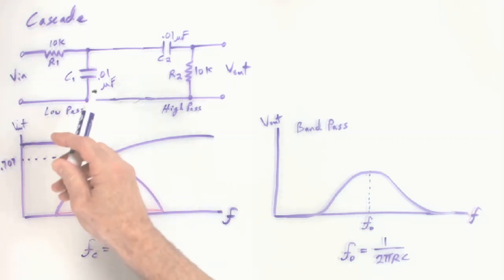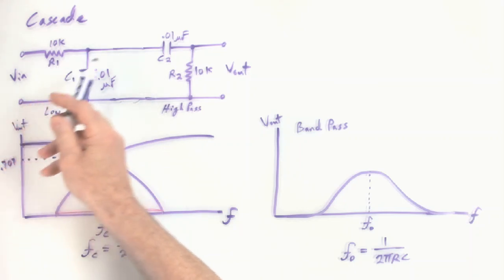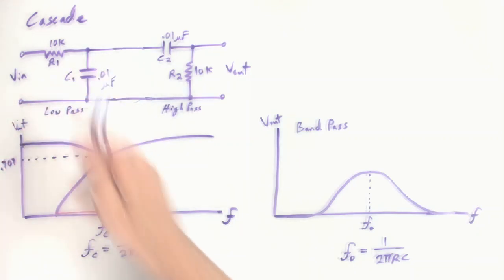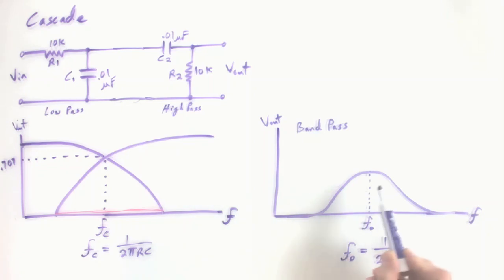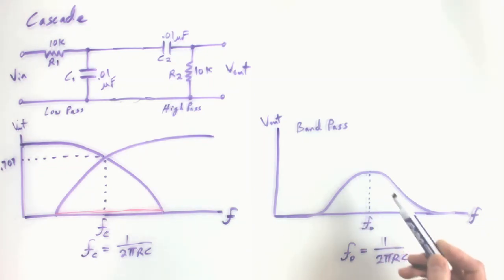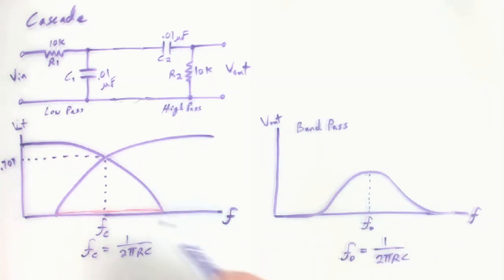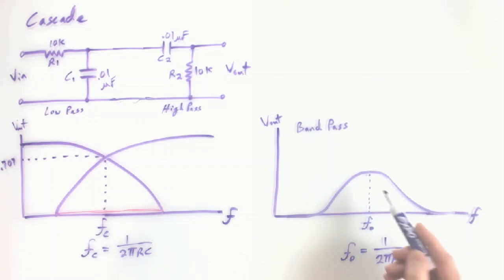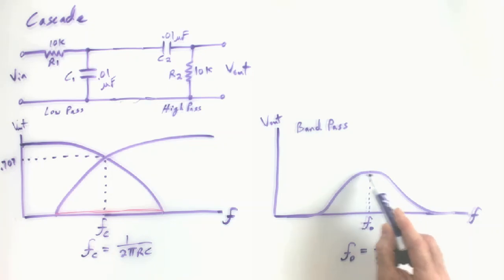In other circuits, you might have active filters where they're buffered, so you don't have to suffer such loss. I mean, I try to do it to scale. When you get through both of those cascaded with no buffering and no gain that you could get from an op amp, your output does come out pretty low, and I'll show you exactly where that point is in a minute.